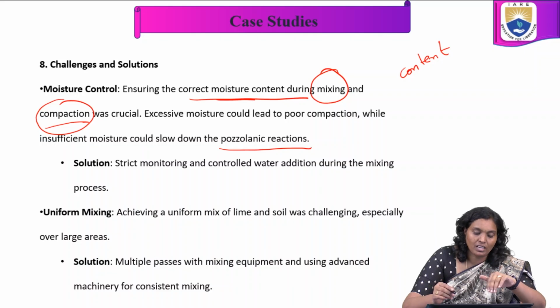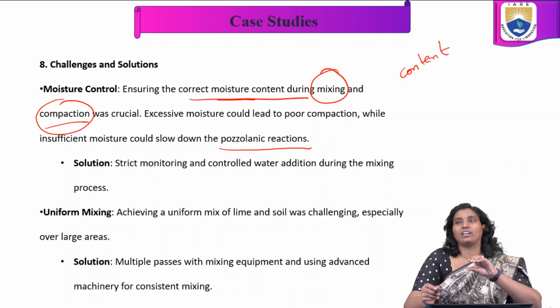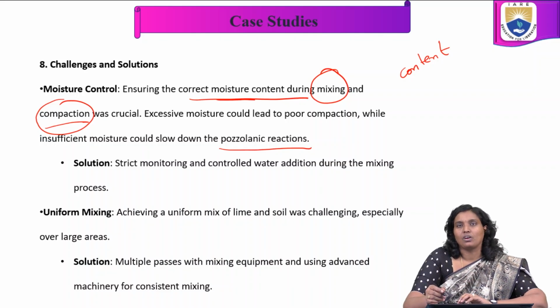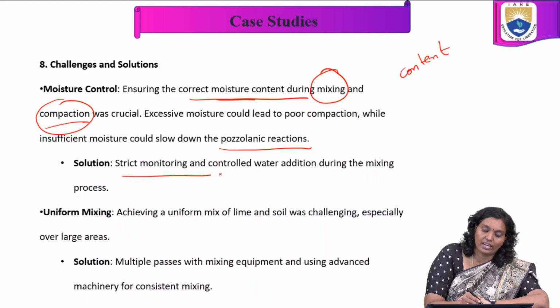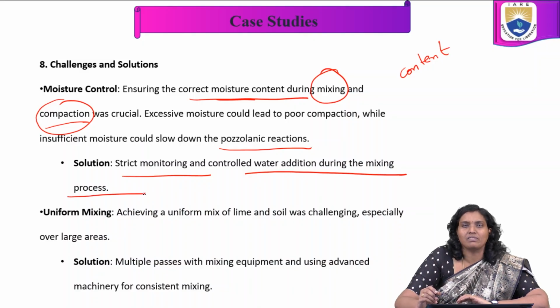So in that particular case, the solution is strict monitoring and controlled water addition during the mixing process, which is important. Strict monitoring and controlled water addition during the mixing process is very, very important. Then the next challenge, uniform mixing.